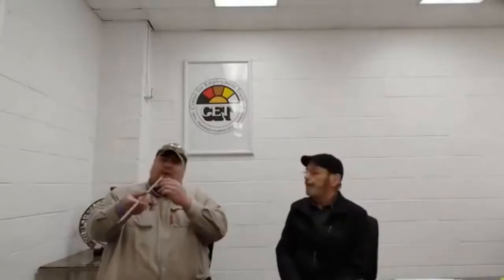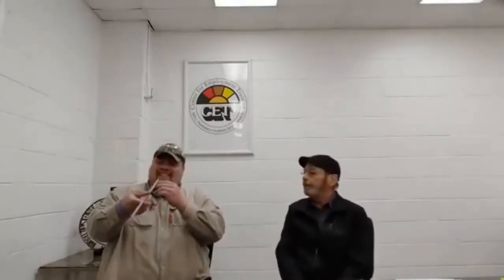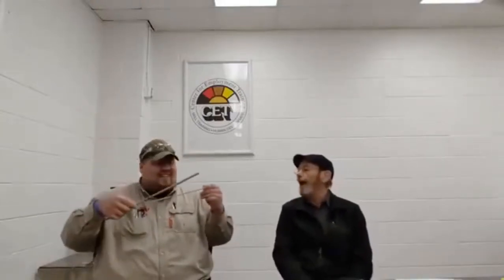So it would be really great when we need areas of very, very good deposit. If you have some very big groove welds to make, then that would be very helpful. So of course, once again, they're going to make a rod applicable for your job. If you had very heavy plate, it would take a lot more runs with a thinner rod than it would with a bigger rod. So they're going to pick out the appropriate size rod for the job.